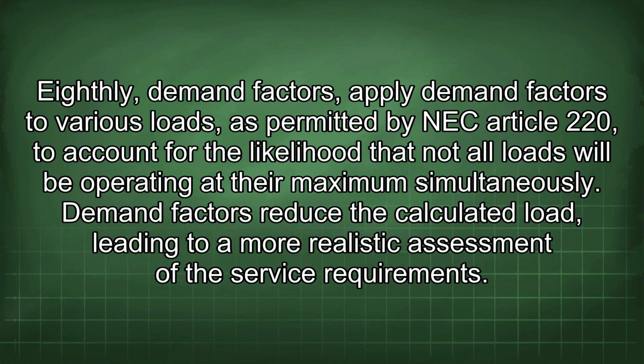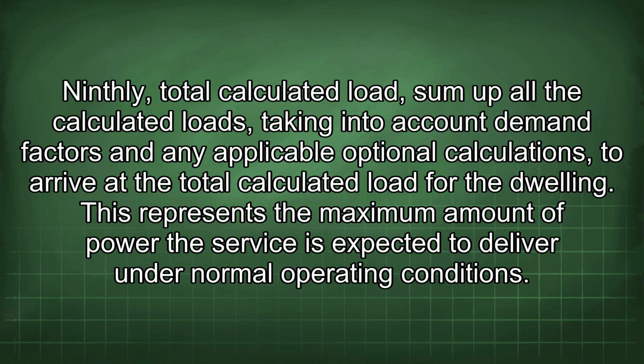Eighthly, demand factors. Apply demand factors to various loads as permitted by NEC Article 220 to account for the likelihood that not all loads will be operating at their maximum simultaneously. Demand factors reduce the calculated load, leading to a more realistic assessment of the service requirements. Ninthly, total calculated load. Sum up all the calculated loads, taking into account demand factors and any applicable optional calculations to arrive at the total calculated load for the dwelling. This represents the maximum amount of power the service is expected to deliver under normal operating conditions.